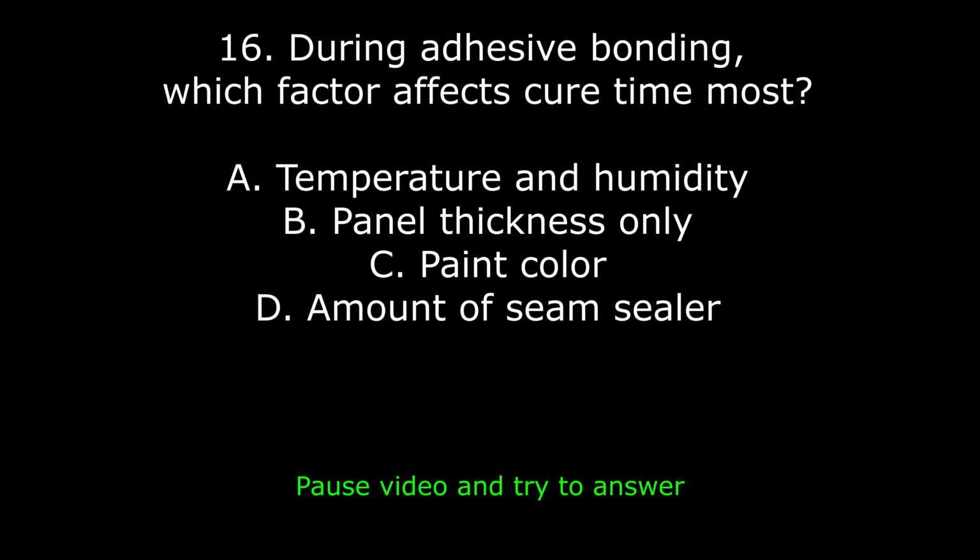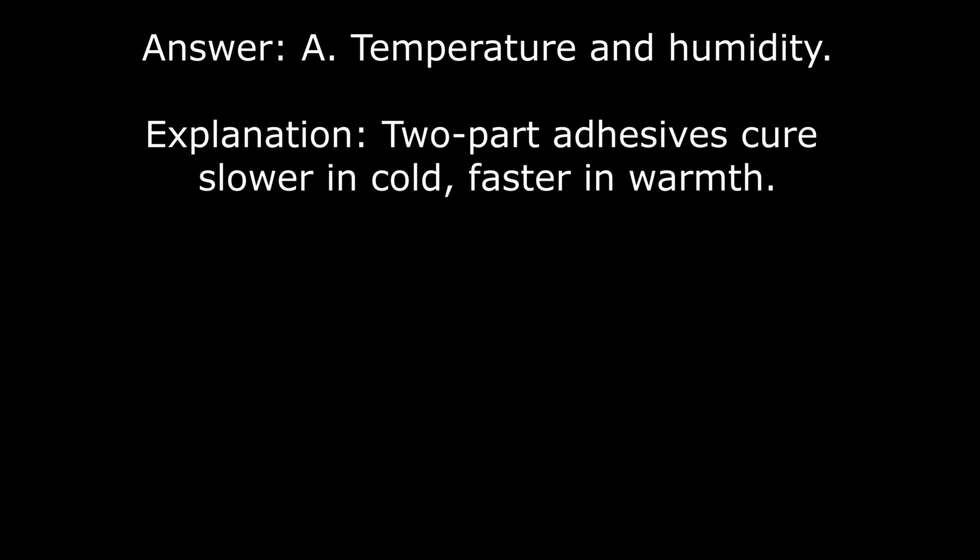16. During adhesive bonding, which factor affects cure time most? A. Temperature and humidity. B. Panel thickness only. C. Paint color. D. Amount of seam sealer. Answer: A. Temperature and humidity. Explanation: two-part adhesives cure slower in cold, faster in warmth.